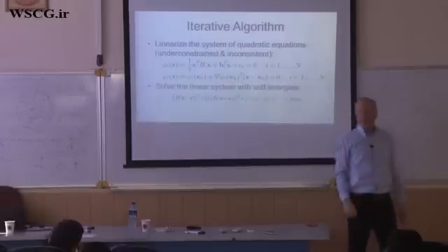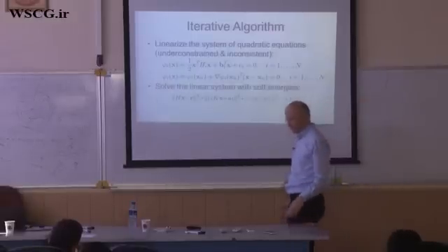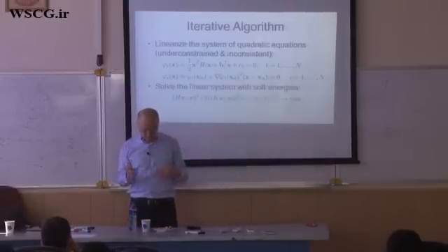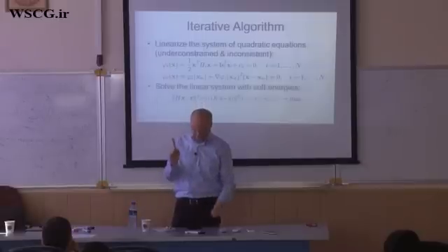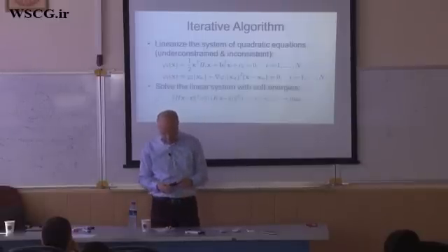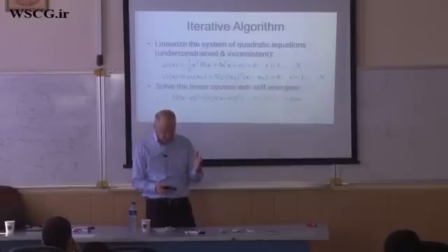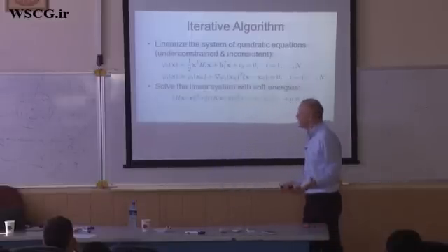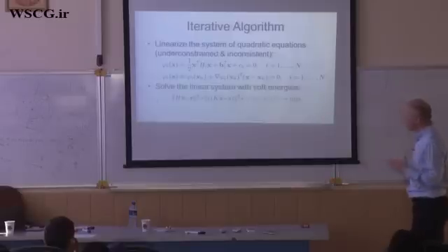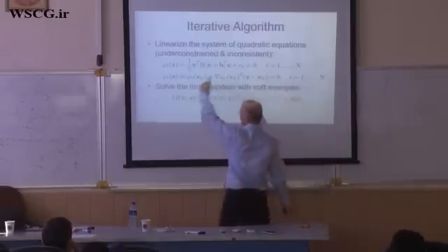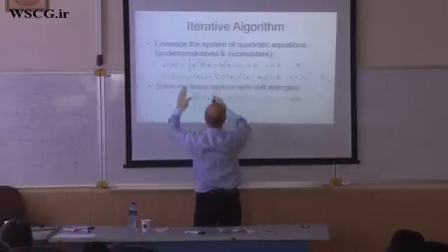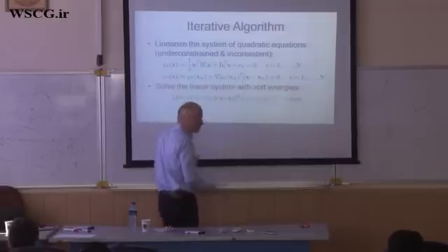But even worse, there may be conflicting equations, because I told you that for example for the planarity of a face, we use all orthogonalities. Each edge orthogonal to a normal, and we get redundant constraints, and definitely due to some numerical imprecision, which is always around, these are theoretically conflicting equations. So this is bad. So what we need to do is solve this system in a least square sense. So we make this residual, left-hand side minus right-hand side squared, as small as possible.